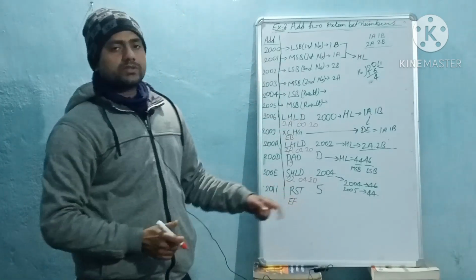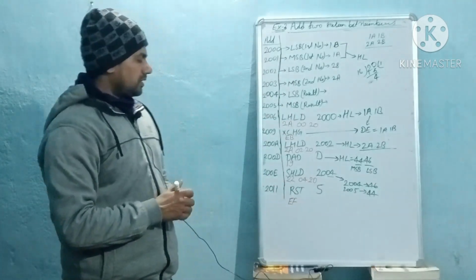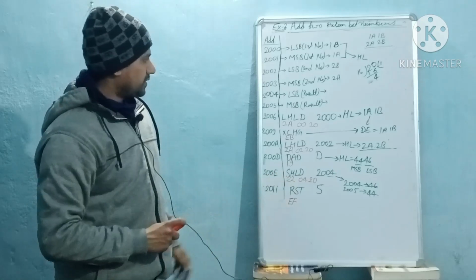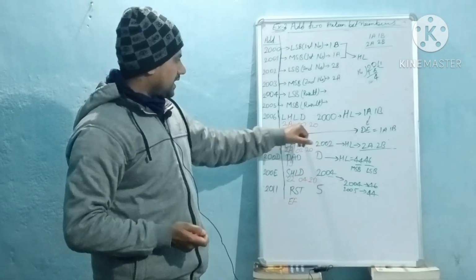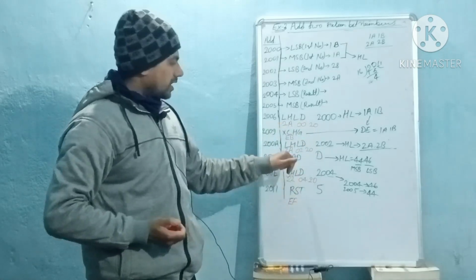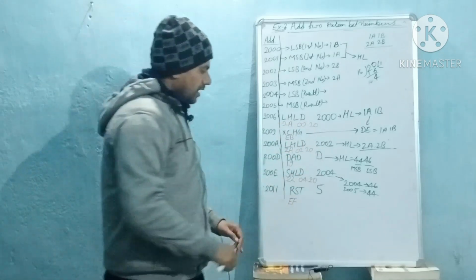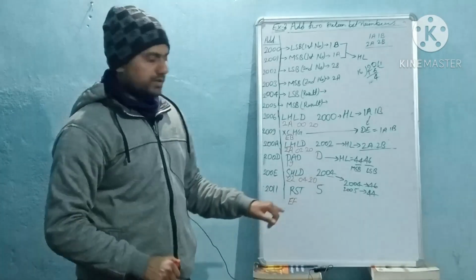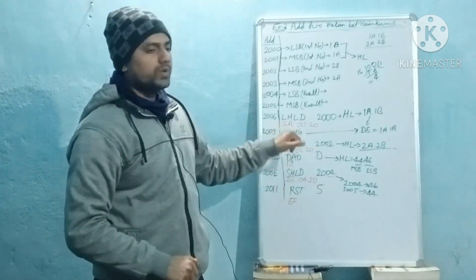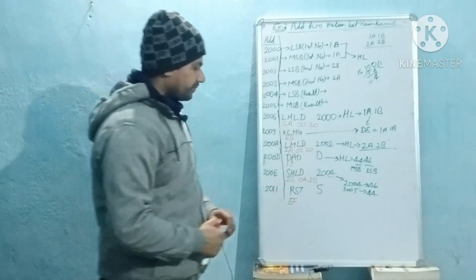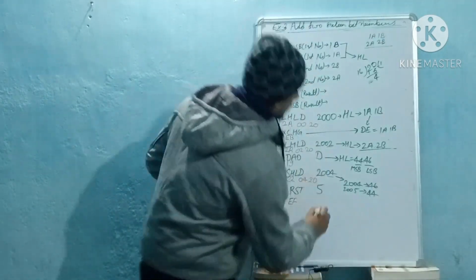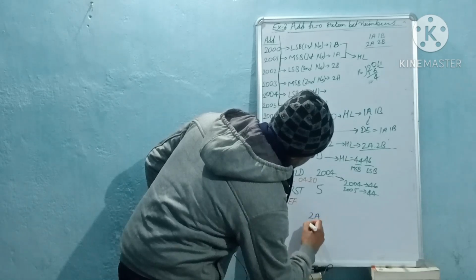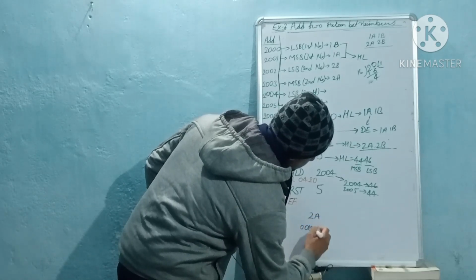You can use another instruction, HLT, also. Here I have used RST5. If you use these hex codes, the hex codes are machine codes, because that is how the processor understands them. For example, if it is 2A, it is nothing but 0010 and